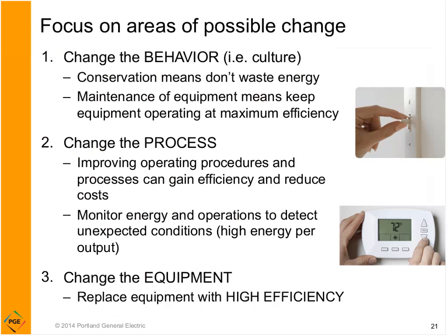The maintenance of equipment can absolutely affect efficiency. If you see your costs slowly going up for a particular piece of equipment, perhaps maintenance of the equipment, something as simple as changing filters more often to get airflow through an HVAC system, can definitely have an effect and show changes on energy bills. So changing behavior is an easy way to get started.